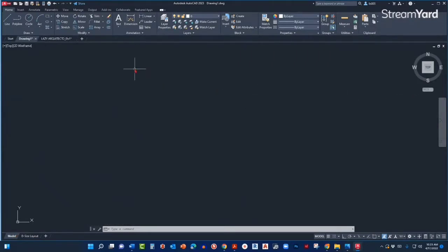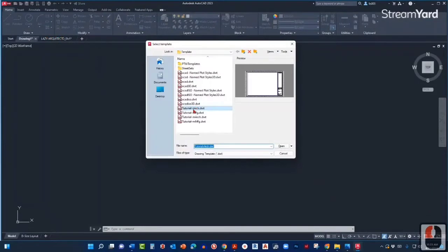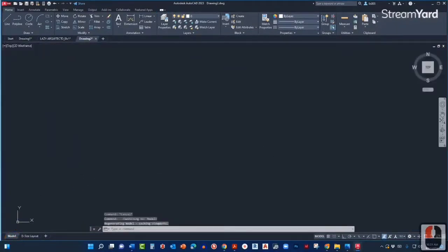And so what I like to do first to draw this is create another drawing. So going over here on this AutoCAD icon, say new and drawing. And then again, I'm gonna pick the Imperial Architecture template that we already explained before. So I'm gonna click open. I'm gonna go to model space by clicking over here. And then what I want to do is